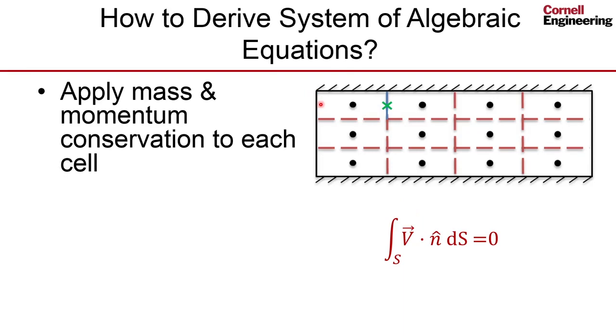And that's the nice thing about the finite volume method, that it's very physical, and so I find it relatively straightforward to understand the big idea of it. When I'm at this boundary, I know what the velocity is from the boundary condition, so again I can calculate what the volume of flow is from the boundary condition, and so on.